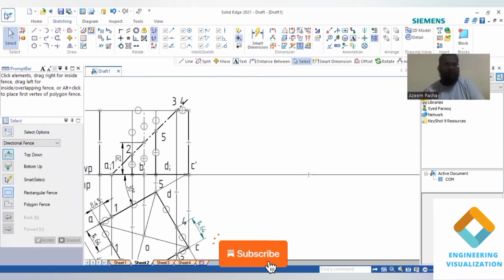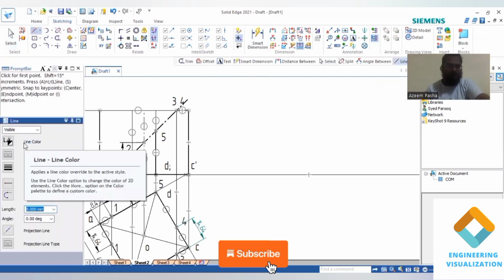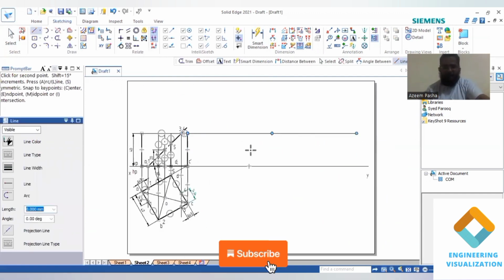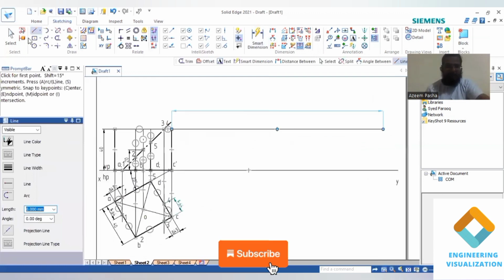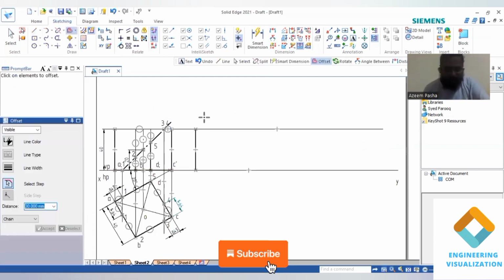Now we draw the development of this. So we're drawing a parallel thin line here, a straight line. We'll draw a vertical line here. Now using the offset command, I'll be taking 4 faces here at a distance of 40.